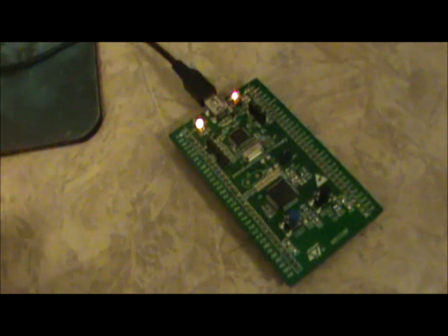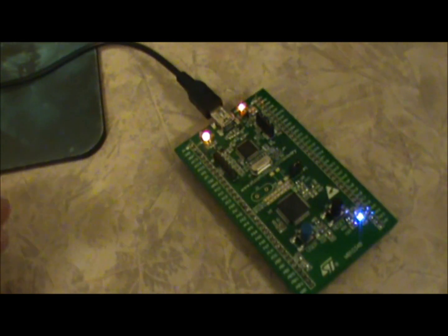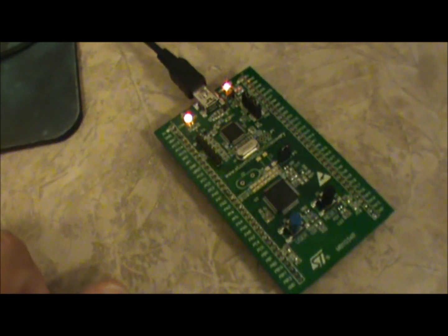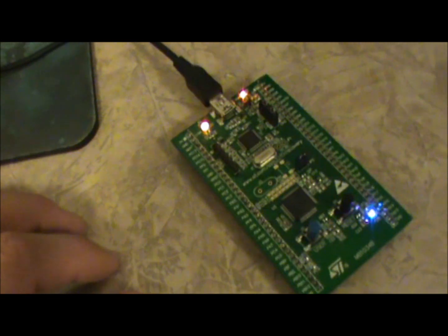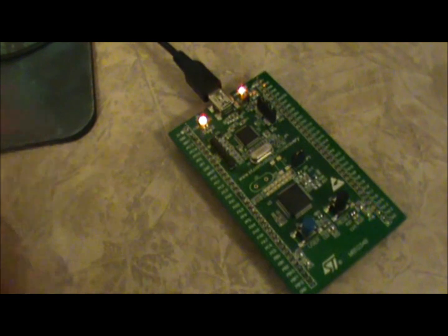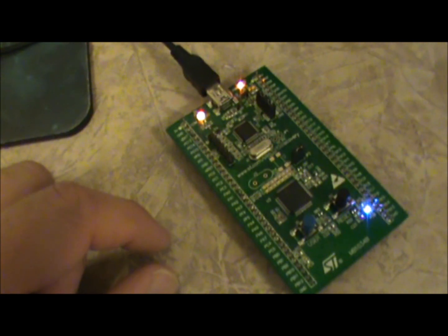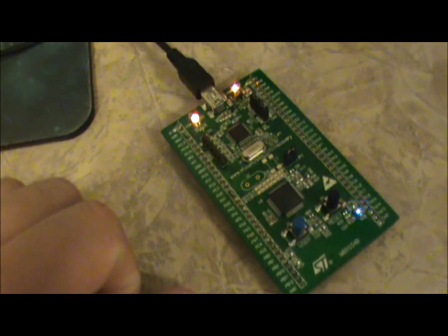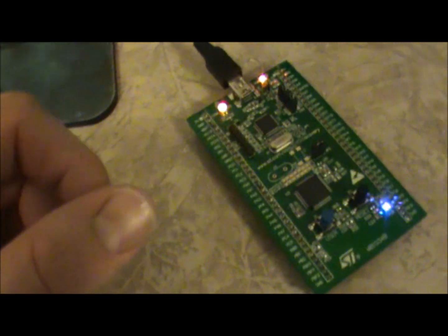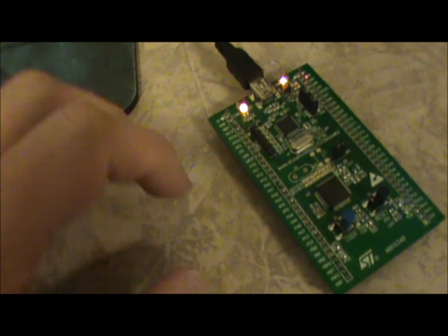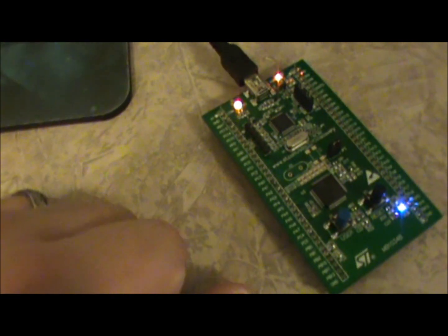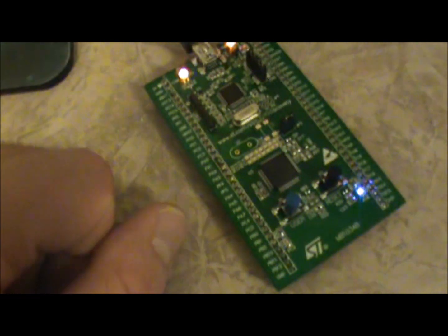Oh, and just as a side note, remember to choose in Keil or MicroVision to have it export a hex file if you're going to use the ST-Link utility software. Make sure it exports that. In the previous video to this one, the software portion of this blink project I'm doing with the ARM, I tell you how to do that. So check that video out if you don't know how to get Keil to output a hex file.